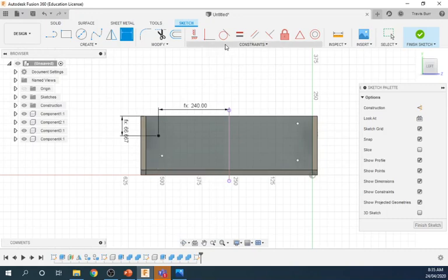And then we've got a couple other constraints. I've got horizontal, vertical. So I'm going to click on that. I want this vertical to that, so that's constrained that into place. I want this horizontal to that, so that's linked into place. I want this one linked to that one, so now that's all linked into place. So vertical, horizontal, that's going to line them up. Escape there. Still though, you can see that this is moving up and down.